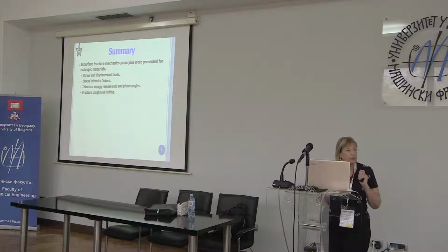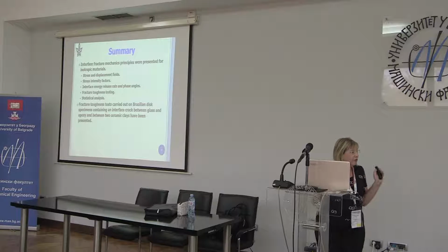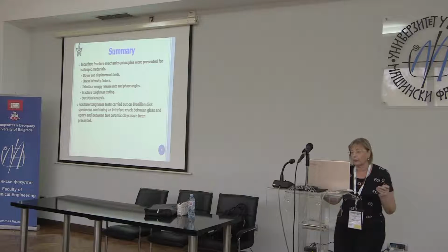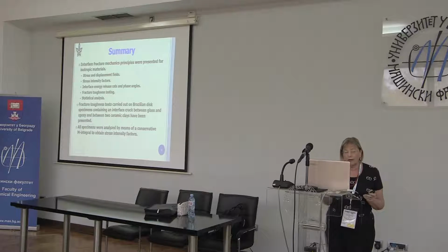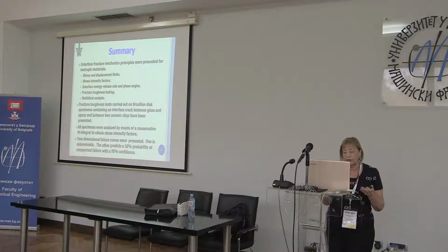We talked about fracture toughness testing and statistical analysis. We carried out fracture toughness tests, which I presented for the Brazilian disc specimen with glass epoxy and 2 ceramic clays. The specimens were analyzed by means of the M integral, both for residual thermal stresses and for applied load.